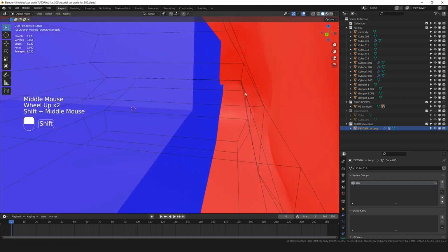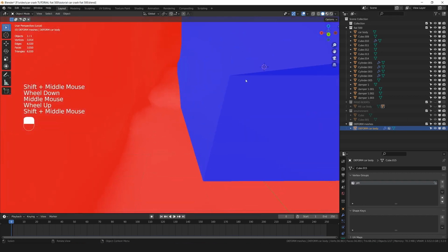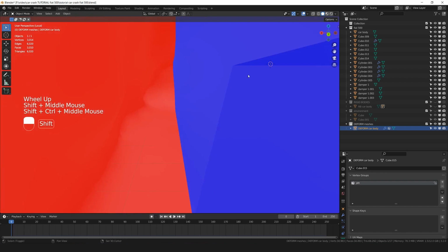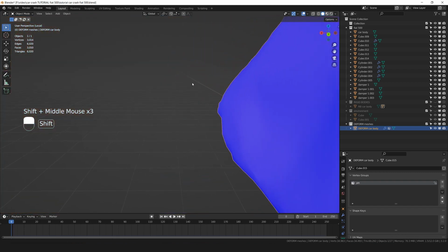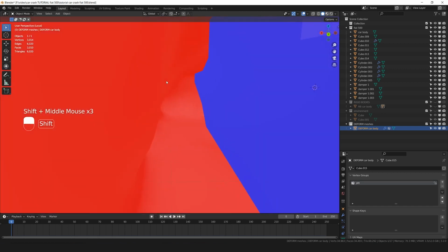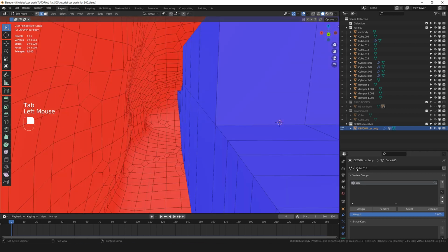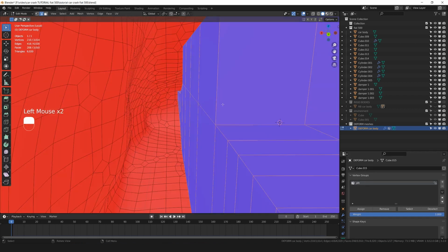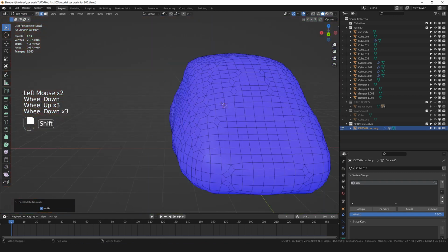But for the internal parts, let's hide the rigid body for now, because we don't need it. Alright, but the internal group, if it's blue like this, it's gonna create a lot of glitches in the collisions, because Blender can't understand which part is the external and which one is the internal. So what we can do is to press Tab to enter edit mode, select only the pin group, so click on select, and press Shift N, and then here in this little menu I'm gonna click on inside. We have inverted the normals.